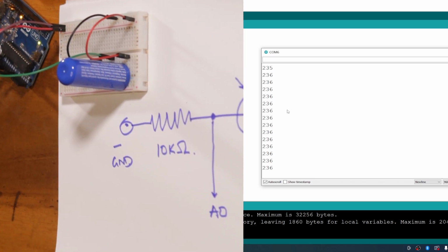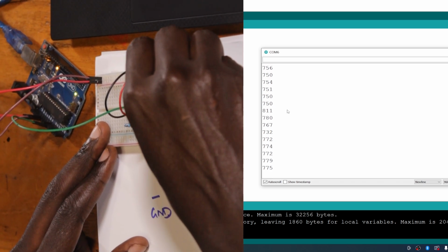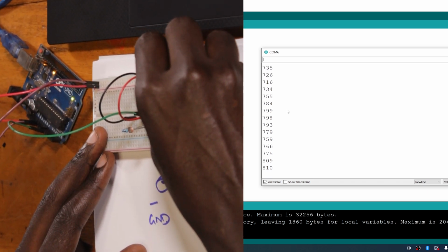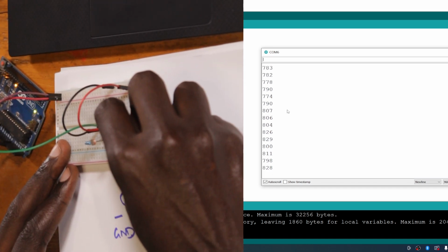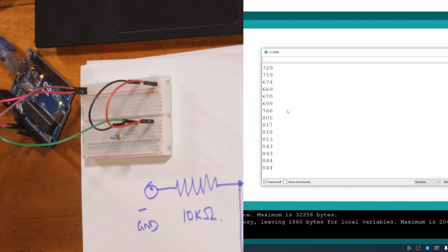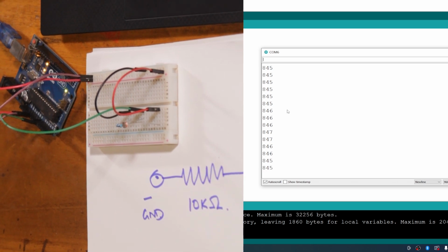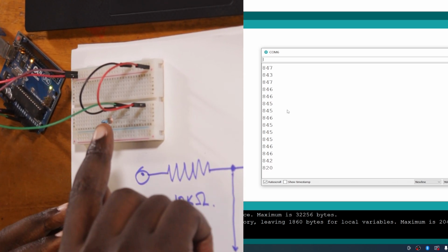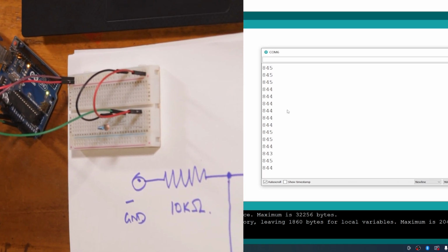to 200. Now, one thing that you have to be really mindful of is this is a very sensitive circuit. So any small interference here, any small misconnection, you might get a lot of, if you notice every time I touch something, the value keeps jumping up and down. So you need to make sure that it's actually very well fixed, otherwise your values will keep jumping. If you don't see any difference as you put your hand or put a light, then know that there's something wrong with your circuit. But this is what it should look like.